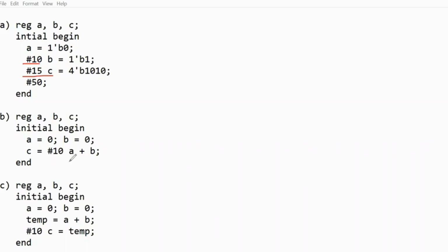That's why for non-blocking assignments, we write using the intra assignment, where the delay is internal, that means on the RHS side. Whereas inter assignment delay is also like a regular delay. For blocking and non-blocking assignment, this 10 will be added to the next statement.